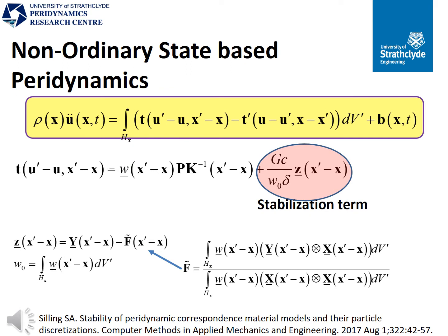Although non-ordinary state-based peridynamics is very suitable to link classical continuum mechanics and peridynamics, it has a zero energy mode problem. Even under steady-state conditions, we can observe unphysical oscillations in the displacement field.